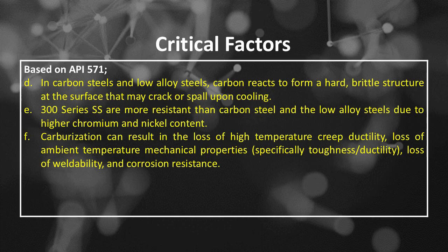Number E, 300 series SS are more resistant than carbon steel and low alloy steels due to higher chromium and nickel content. And number F, carburization can result in the loss of high temperature creep ductility, loss of ambient temperature mechanical properties, specifically toughness and ductility, loss of weldability, and loss of corrosion resistance.